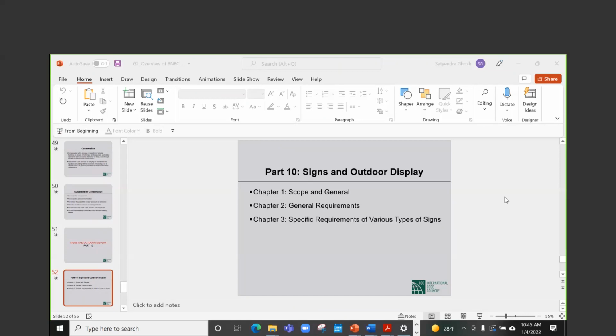As I said, an over-reinforced member fails explosively, all of a sudden, without warning, and that is not a good situation to have. So if evaluation indicates that certain beams in a structure are over-reinforced, it will be very desirable to bring those beams into compliance, and that compliance should be with the new code. Now, if 100 beams in a building are out of compliance, then the trigger will go off and you may have to bring the whole building into compliance with the new code. I wouldn't be able to tell you without knowing the extent of it. But this is an unsafe situation and should be taken seriously. And yes, your building is out of compliance.